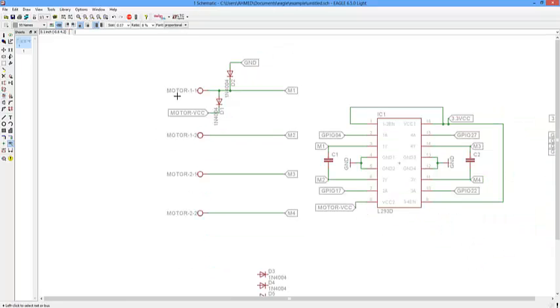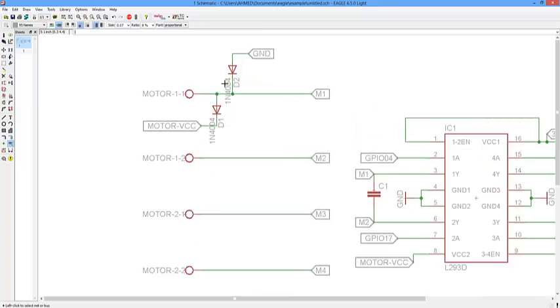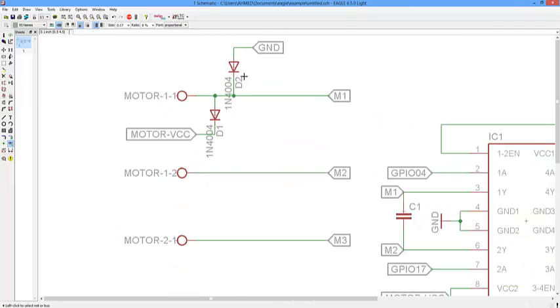Yeah. So I was saying before, the huge humiliation I had is that if you understand the basic electronics, these diodes will never conduct because the anode is connected to ground and the cathode is connected to VCC. There is no possibility of them conducting. When will they conduct? When the coils inside the motor want to charge the current inside them, they will conduct either into ground or VCC, but they will not conduct back inside the H bridge, which basically would burn the H bridge.